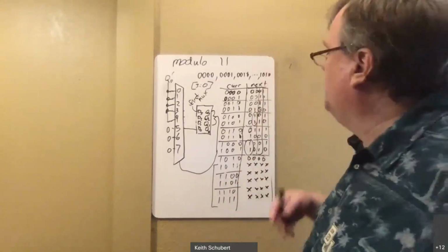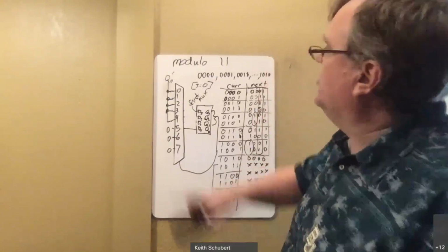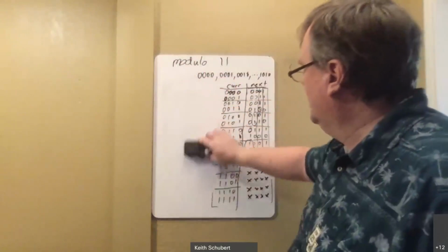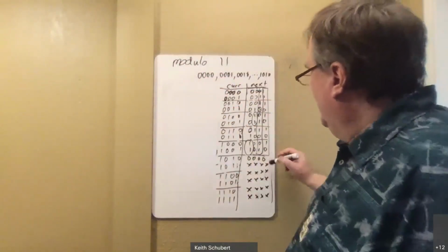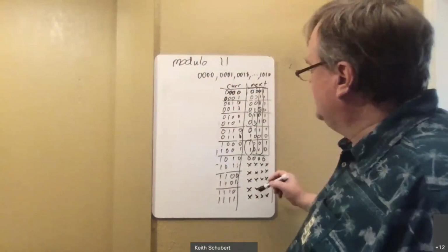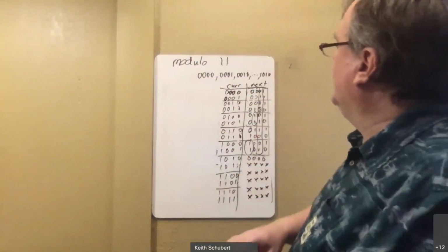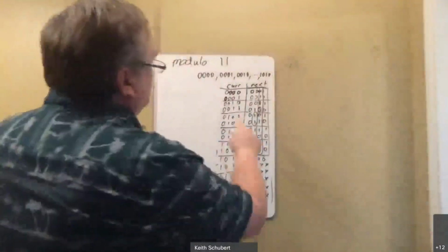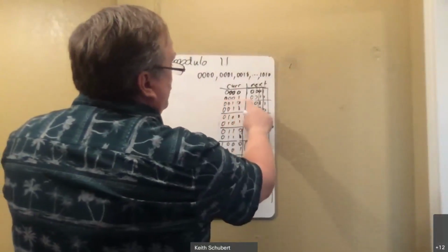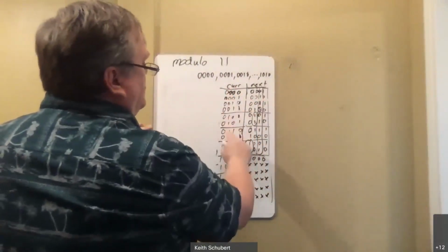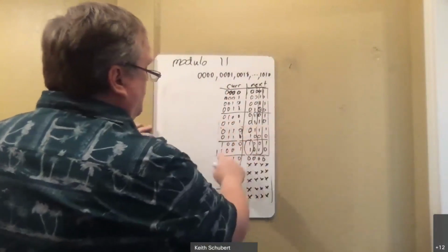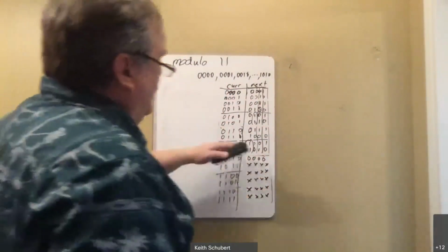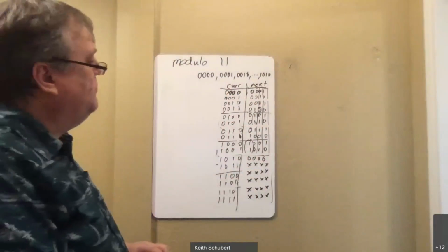The way you can group things so that they get distributed around, I'm going to erase this. Since you want one of these in every one of the sets, if you look at these, you've got groups of 4 because it's a 4-input mux, which means you're going to be making groups of 4. If I use the most significant bits, you'd be grouping them like this. That doesn't really help you.